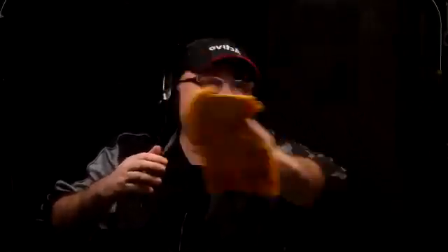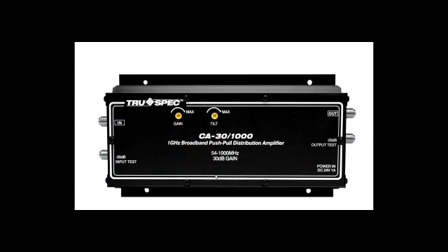Let's say you have one of the older systems that is still in use in some schools or bigger facilities, mostly schools, and some of them are still intact. Because let's say 10 years ago they spent $200,000 on installing it, and they're going to try to get as much mileage out of it as they possibly can. So this would be the amplifier here with the cable TV signal coming from the city. That's the signal coming in. This little triangle is the amp, the RF amp, radio frequency amp.